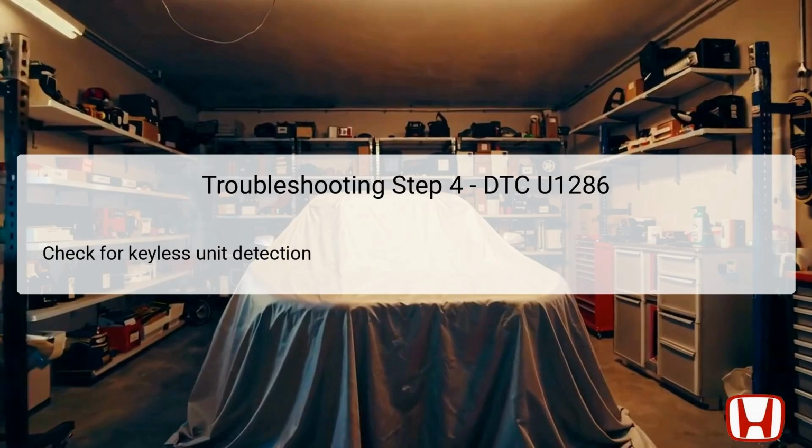From the Body Electrical System Select menu on the Honda Diagnostic System, HDS, you will need to access the BCAN control unit's information. This step involves checking whether the keyless access control unit is detected by the system. If the unit is detected, it suggests that communication exists, at least to some extent, between the gauge control module and the keyless access control unit. In this case, you will proceed to later troubleshooting steps for deeper analysis.